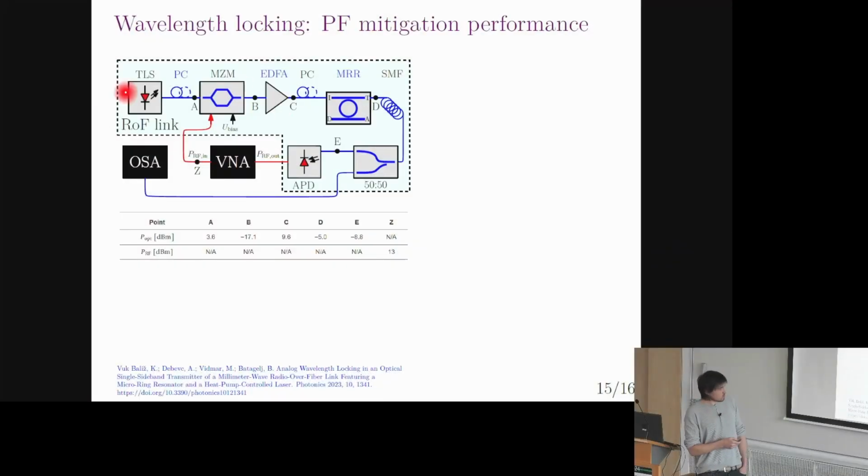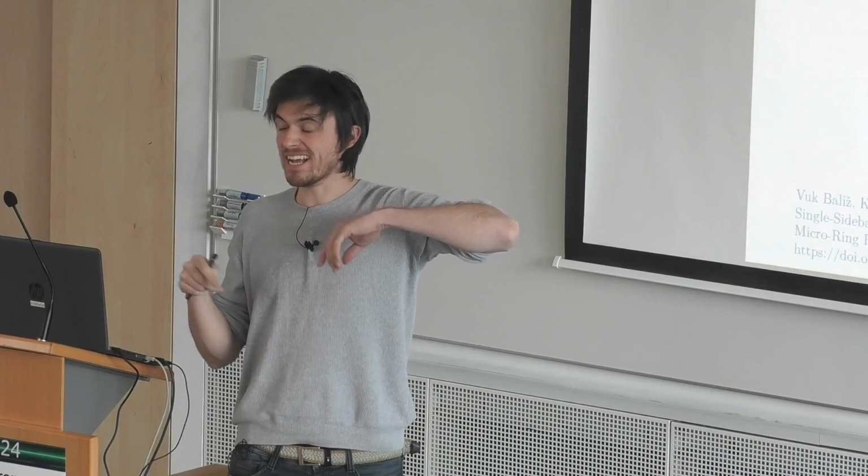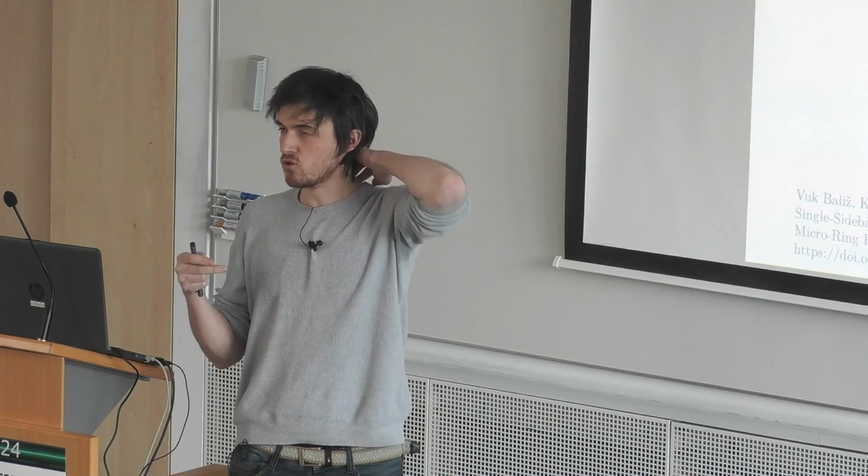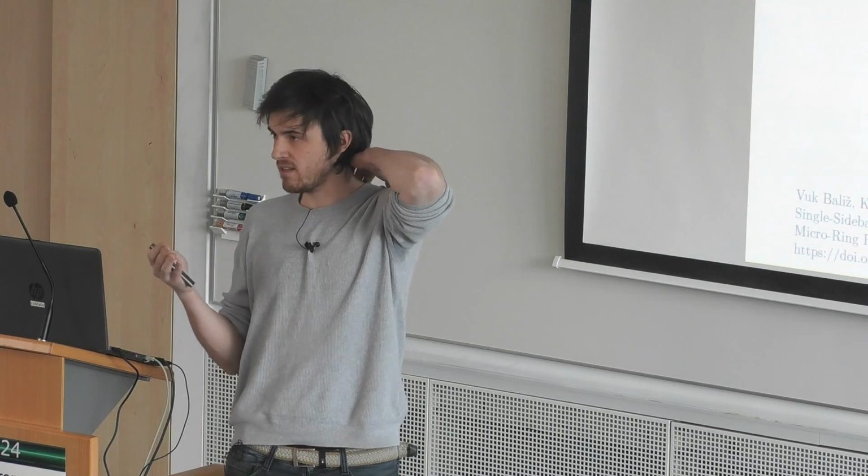Yeah, well, let me just show that figure here. The problem was, in order for us to perform the experiment, we had to use a non-optimal configuration of the Mach-Zehnder intensity modulator. We didn't really have it biased at the quadrature point, the -3 dB point, but we configured it for a different carrier to sideband ratio in order to have the sidebands at the drop port expressed enough to have a relevant feedback signal.